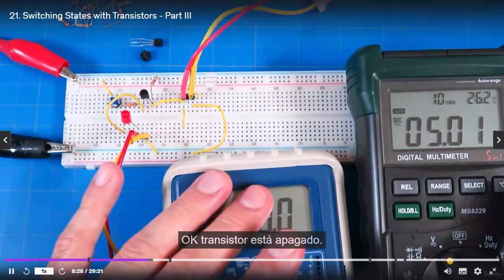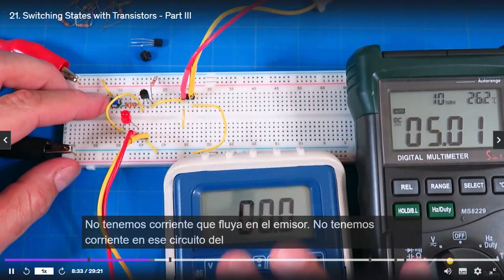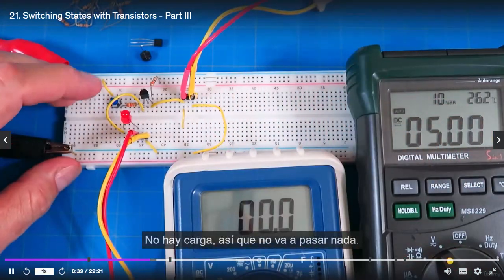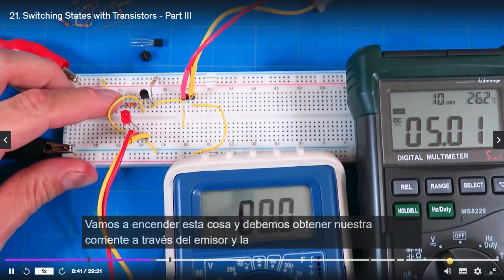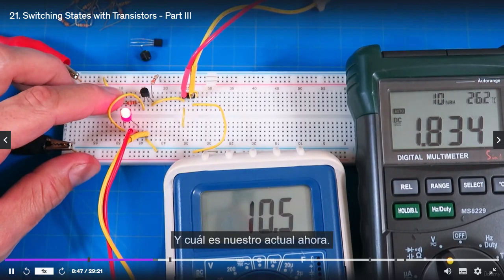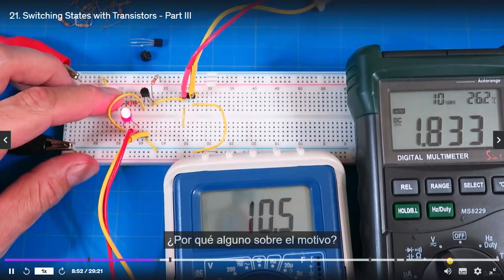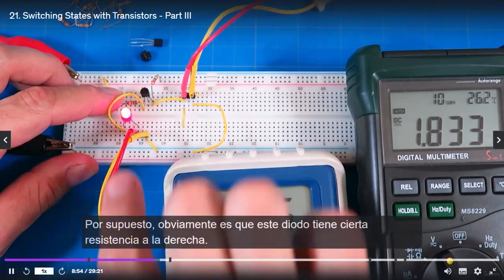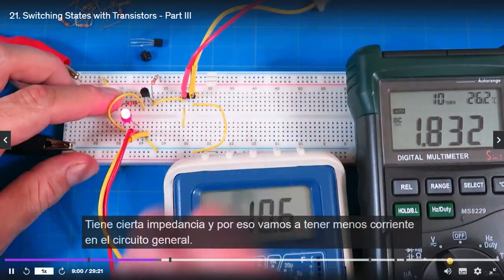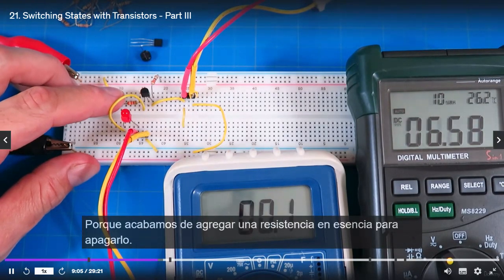Okay, transistor is off. We've got no current flowing in the emitter, no current flowing in the collector emitter circuit at all. We've got 5 volts at the collector. There's no load on it, so nothing's going to happen. We're going to turn this thing on, and we should get our current through the emitter, and this LED should turn on, and it does. And what's our current now? It's 10 milliamps instead of 16.7. Why? Anyone? The reason, of course, is that this diode has some forward resistance. It has some impedance, and because of that, we're going to get less current in the overall circuit, because we just added a resistor, in essence, to it. Turn it off. There we go.